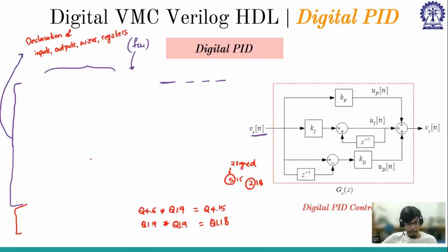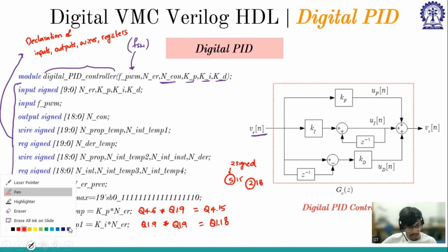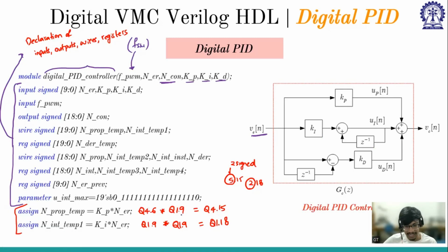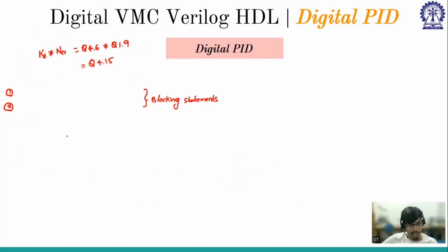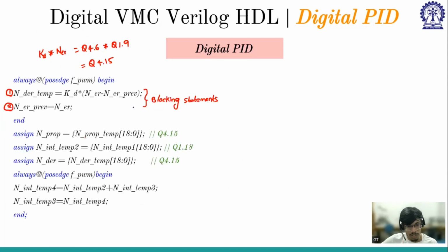But what happens is whenever we are multiplying, say, 10 bit with 10 bit, this will be 20 bit, because we know that there is one redundant extra sign bit which we should ignore, but the simulator does not know. So it will give 20 bit here, and here also 20 bit, as we are multiplying two 10-bit numbers. But we know that it should not be 20 bit. In fact, it should be 19 bit because there is one redundant sign bit.